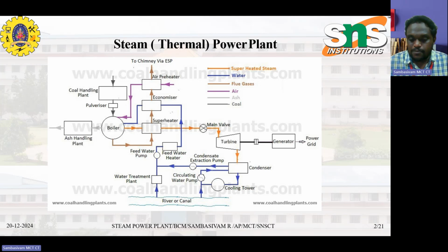The steam hitting the turbine blades loses most of its energy and leaves the turbine as low pressure steam. The low pressure steam enters a condenser. The cold water circulates in the condenser from the cooling tower. Here, the low pressure wet steam is converted into water. After that, the condensed water is passed to the economizer, where it gets heated, and finally the feed water enters the boiler by a feed water pump to repeat this cycle. So the cyclic process is done.